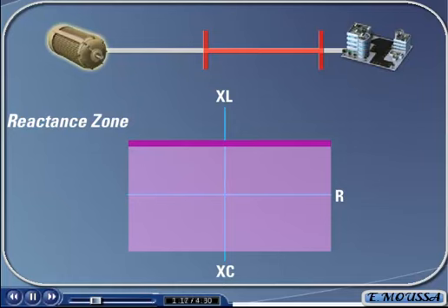If the fault does have a high resistive impedance, this indicates that there is a load on the transmission line, and the fault is most likely not on the transmission line. This type of zone is usually never used to trip a transmission line on its own, but is normally used to supervise another distance zone of protection.